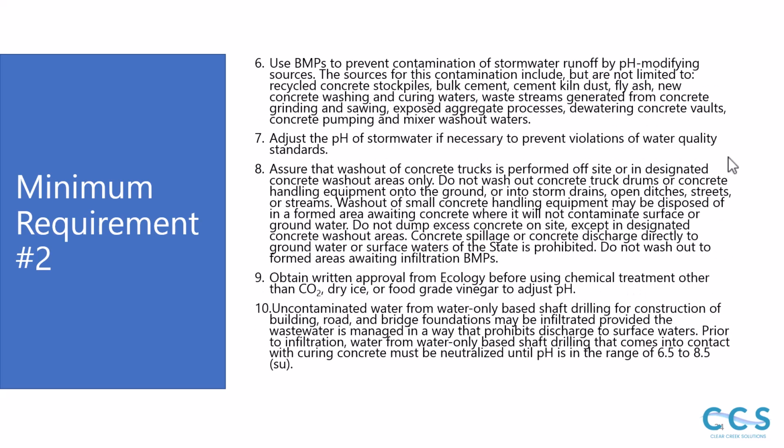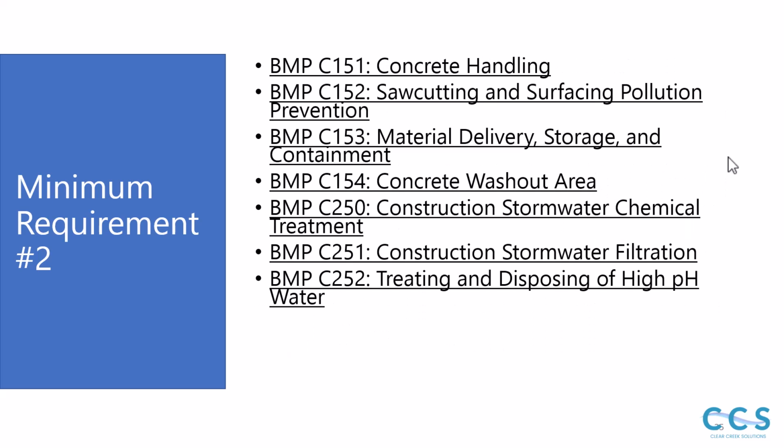Use BMPs to prevent contamination of stormwater runoff by pH modifying sources. Adjust the pH of stormwater if necessary to prevent violations of water quality. Assure the washout of concrete trucks is performed off-site or in designated areas. Obtain written approval from ecology before using chemical treatment other than CO2, dry ice, or food-grade vinegar. Uncontaminated water from water-only based shaft drilling for construction of building, road, and bridge foundations may be infiltrated provided the wastewater is managed in a way that prohibits discharge to surface waters. Then there are 7 applicable BMPs there.